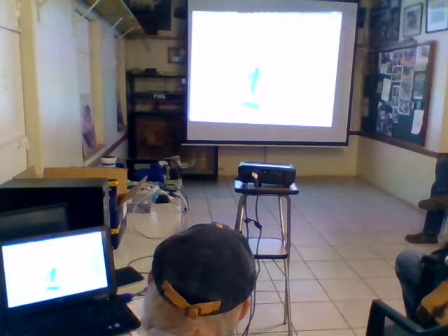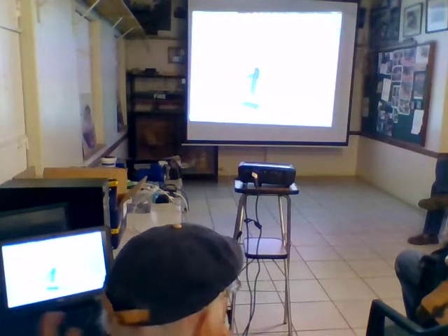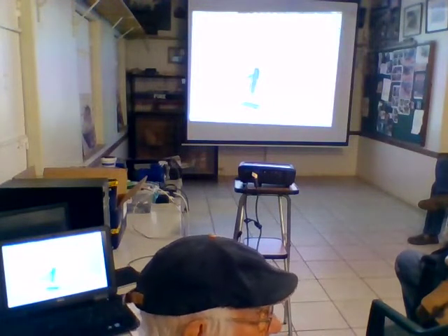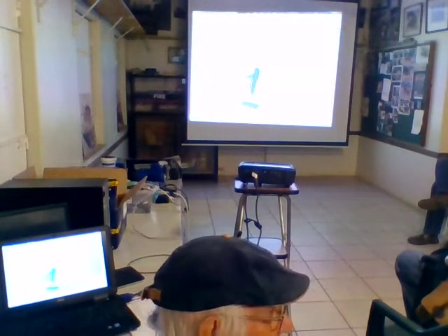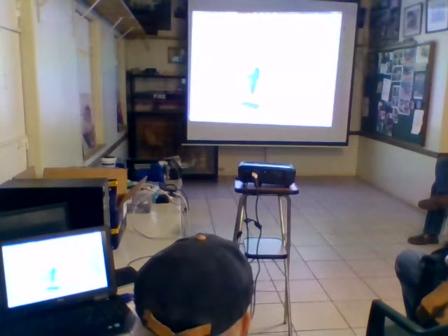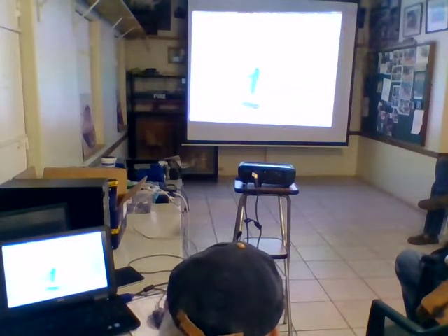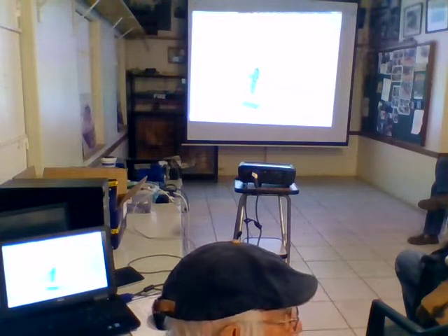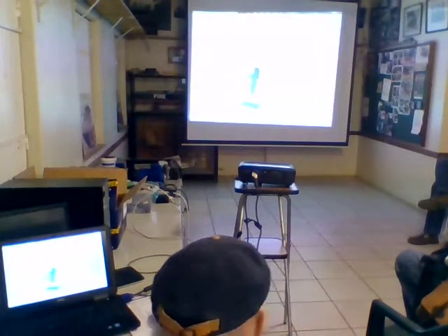You'd be surprised, but the nuts and the lead screws themselves, they also have to select their sizes right. I've got 16mm lead screws in this, and I'm still not 100% sure that is sufficient. Maybe one should go in a little bit higher.